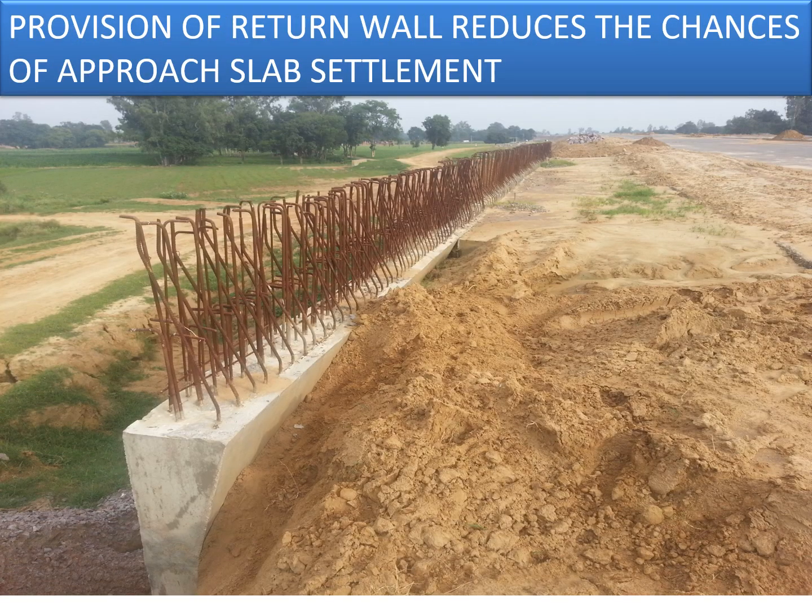So if you see the examples, generally we provide wing walls with the structure. Now, the problem associated with the wing wall is that it is constructed in a sloping direction, which is moving away from the cross section of the road. So what happens is you have a weaker section or a weaker zone which is in line with the wing wall, and thereby the possibility of erosion of the soil is higher.